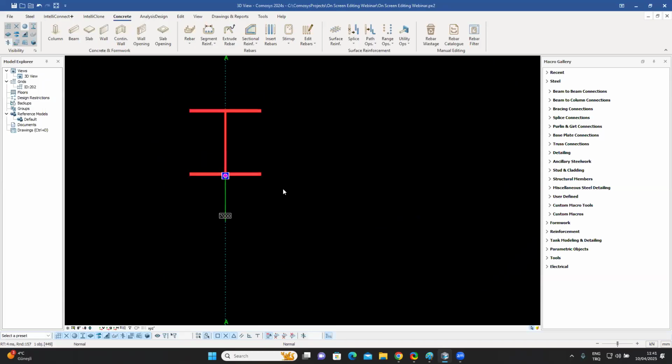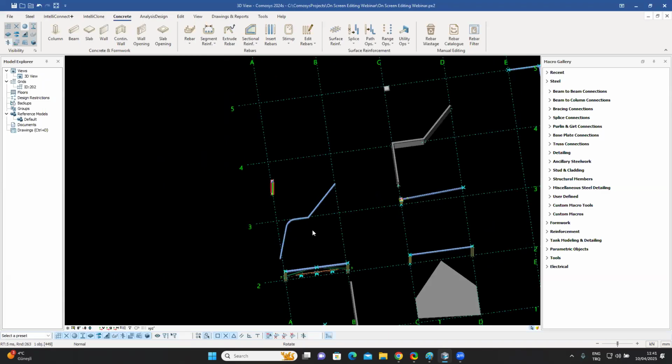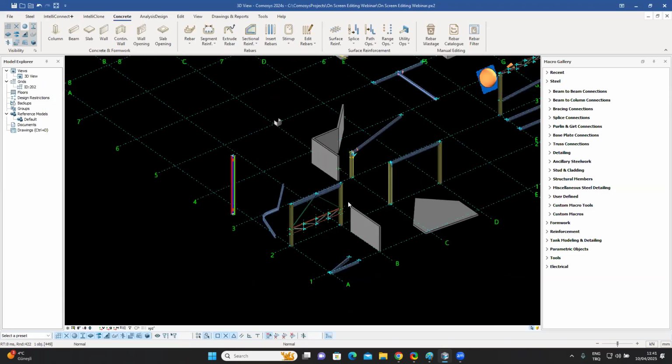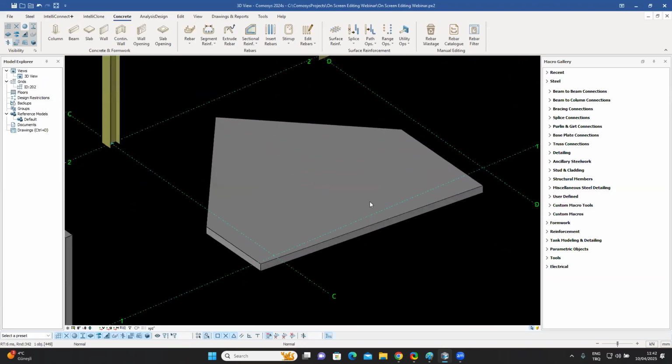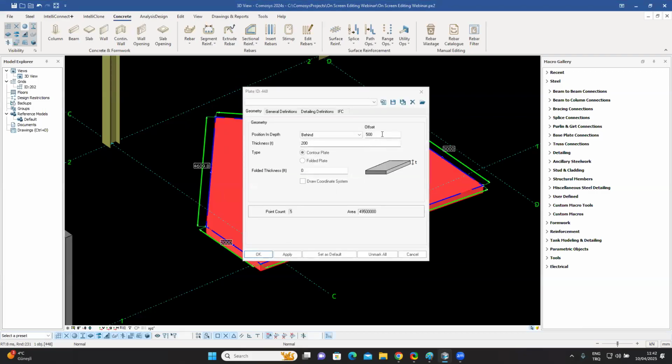And then if I press Control E, I can do the position in depth. So very convenient ways of moving your offsets around by using keyboard shortcuts. Now with the plate element also, I don't have the Control Q option because there's no rotation over here, but I do have the Control W option, which is useful. Let me just remove the offsets over here.